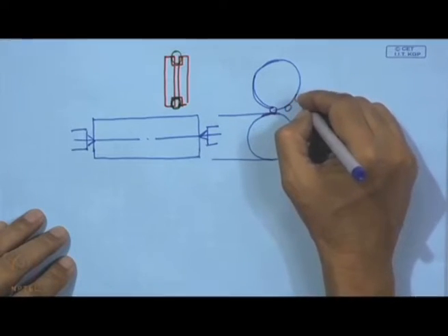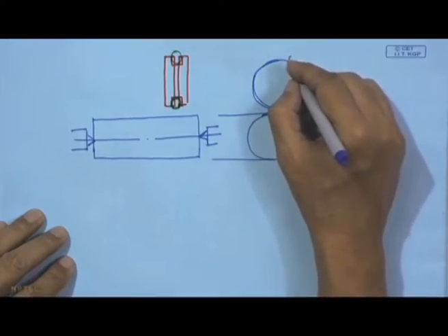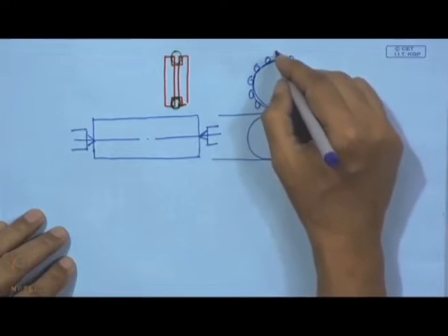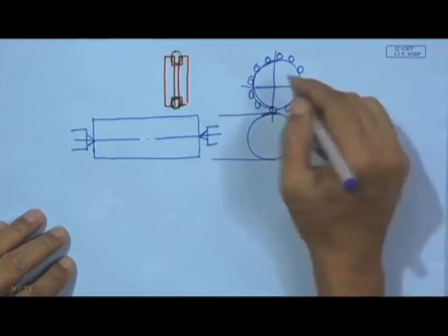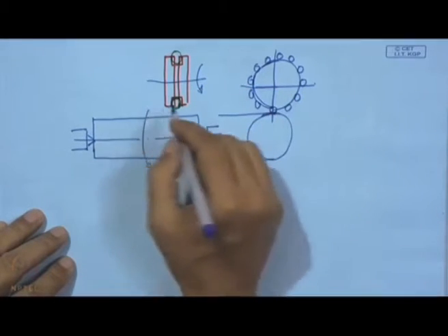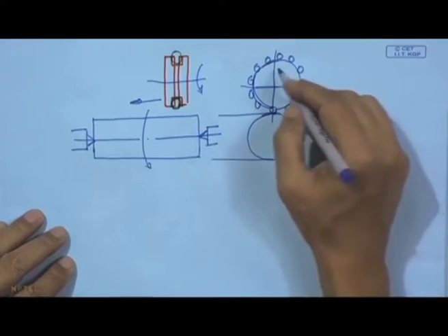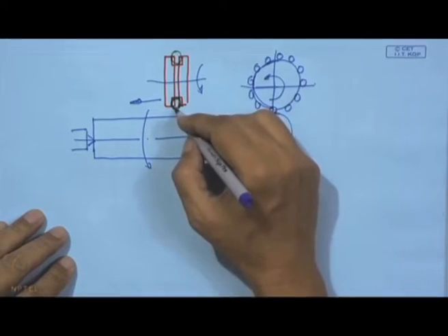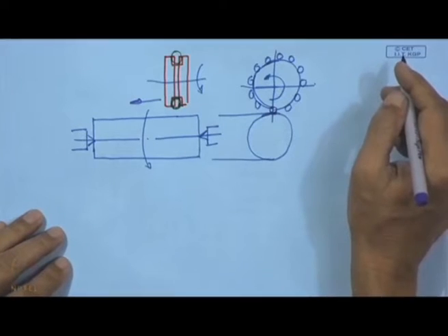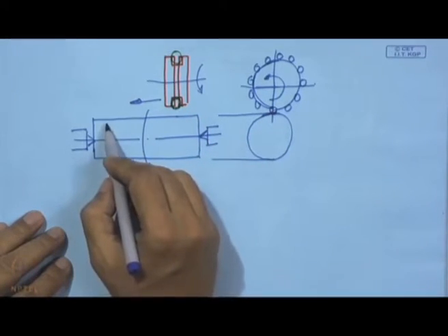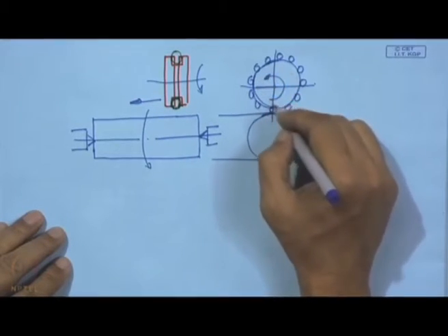And here the balls are retained in a cage. So, in that slot the balls are retained and they should not fall out. So, this will have a rotation, this also has some rotation, and at the same time translation. Now, what happens is it rotates at high speed, and this ball is pressed against this surface. While pressing against this surface, it can do the necessary plastic deformation over the entire surface, and that pressure is created by this centrifugal action.